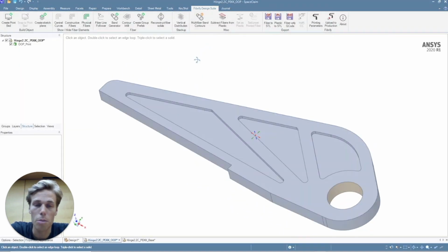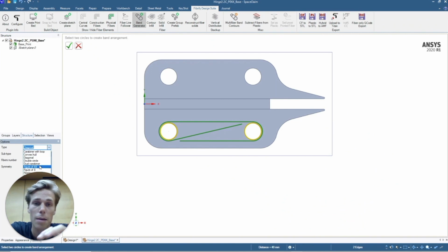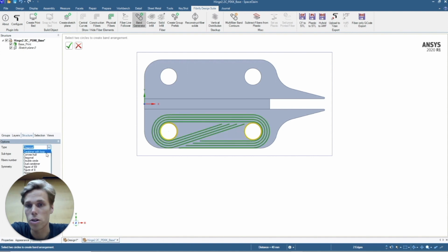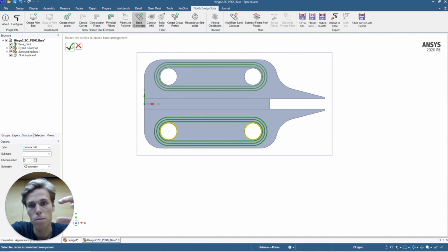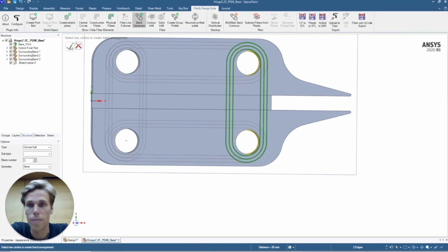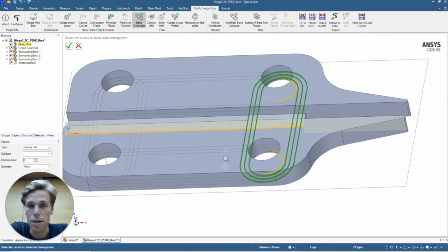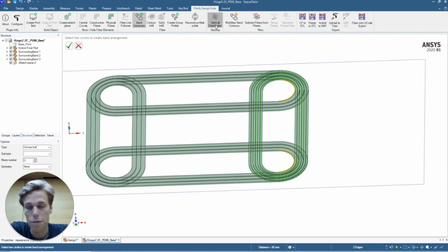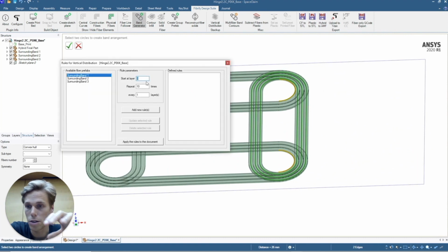And you can either create a geometry from scratch and start placing your fibers and plastics strategically, or you can import a model from any of the CAD tools that you might already use, like CATIA, SolidWorks, or NX. And so what we've tried to do is give you a lot of freedom in how you place your fibers and your plastic throughout the part, but at the same time make it relatively easy so you can quickly generate designs. And so one of those tools is the band generator that allows you to select polygons within your part and have different fiber bands go around and between those polygons.